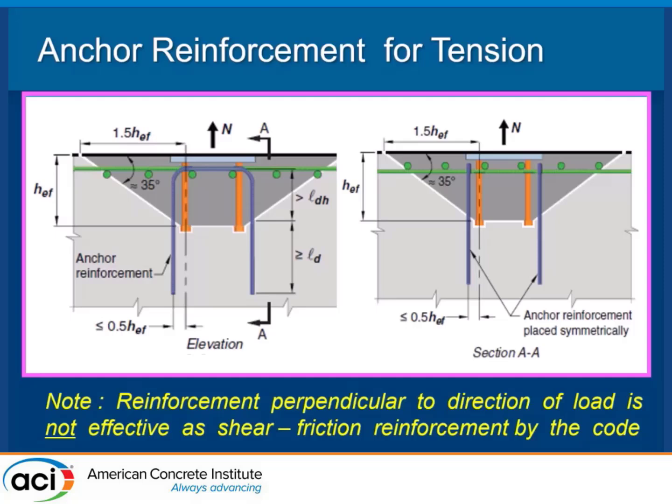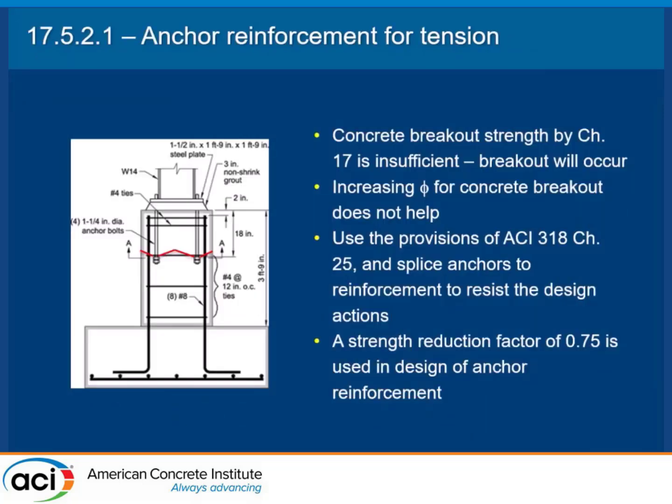Am I truly in a situation where I don't have any reinforcing steel around? Do I have some reinforcing steel around that I'll take if I need it? Or do I need to design some reinforcing to actually just preclude the type of failure?